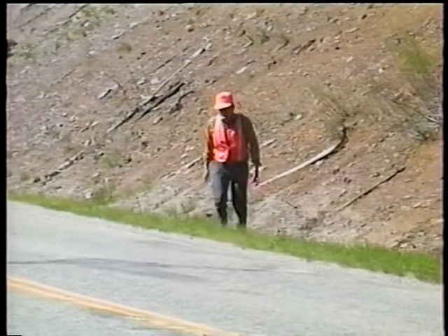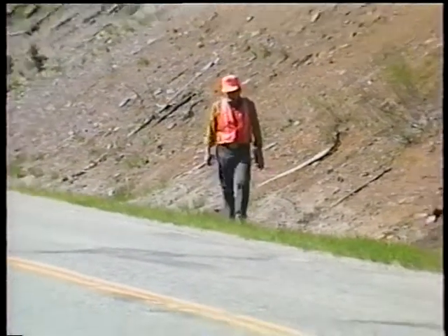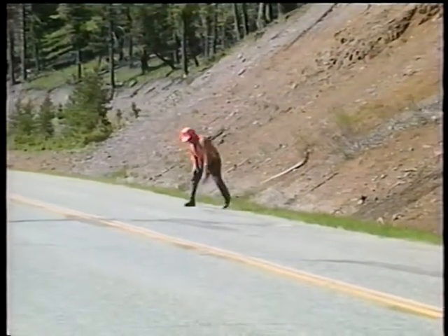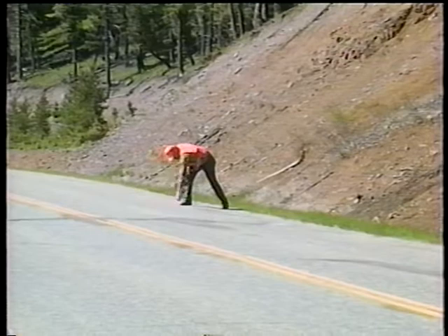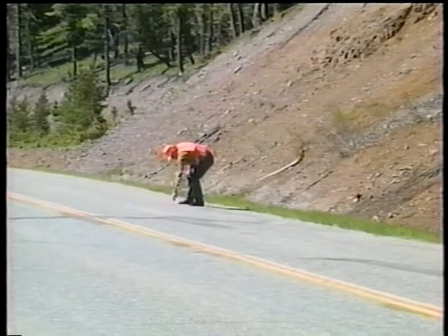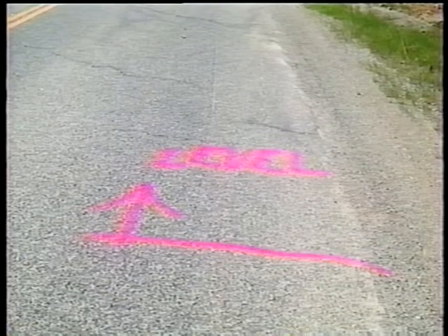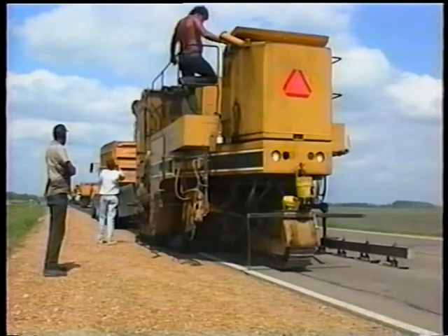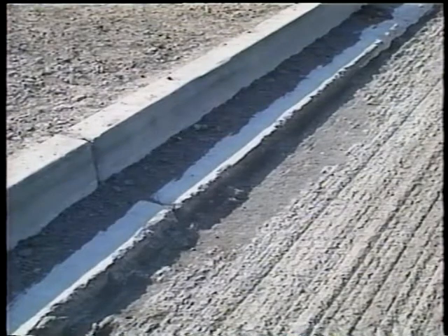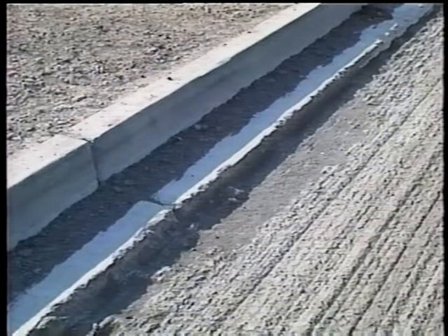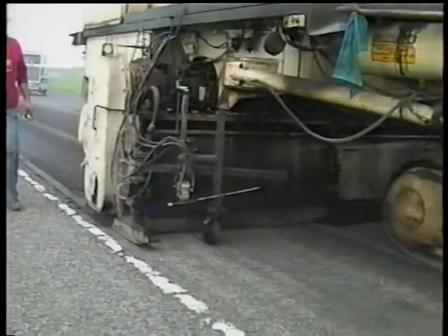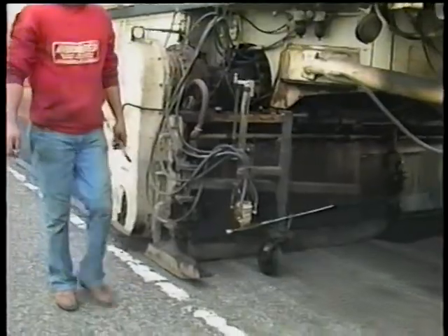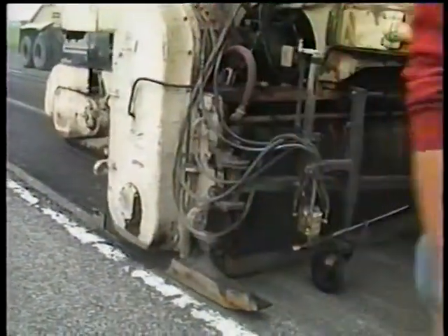Some areas of the existing surface may need to be repaired before the road is paved. The locations and extents of these defects, such as potholes and areas needing pre-leveling, are typically marked on the pavement. See to it that this repair work is done properly. Along with pothole repair and pre-leveling, many projects specify milling. Milling is often used in urban areas so that the new pavement will match up with existing manholes and curbs. This procedure is also effective in eliminating wheel ruts.